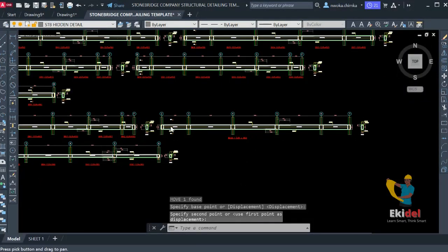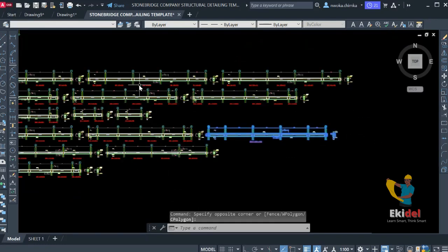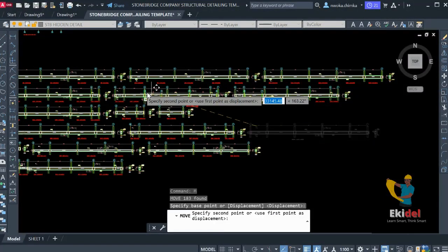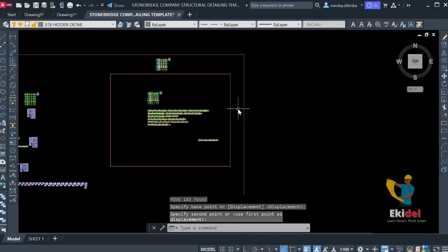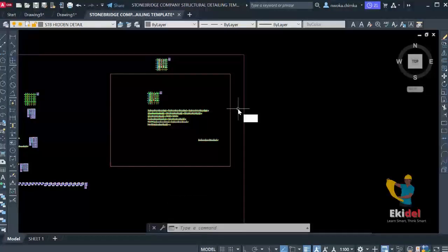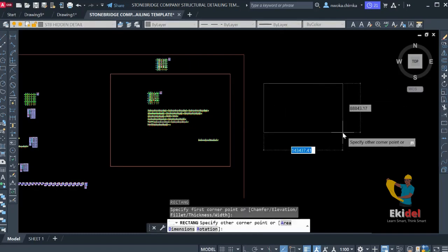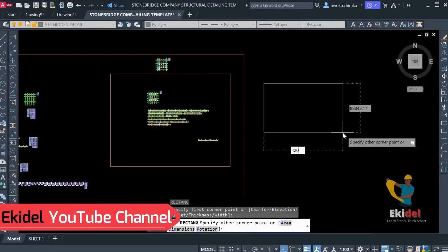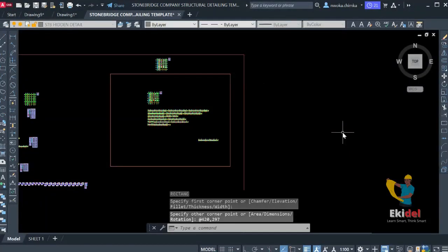Okay, so the first thing I'll do is to separate this one from these other ones because we have not finalized the naming of this one. So just move this from this place where it is. But before then, I'll just keep it here for a bit. Then I'll make an A3 paper size, which I'll do using rectangle, and then click enter, and then click on this and put in my A3 paper size, which is 420 comma 297, and I'll press enter.